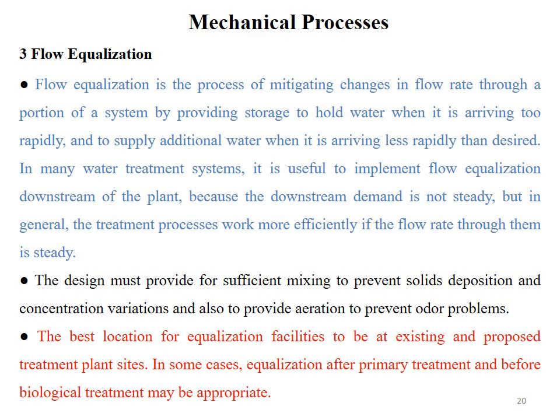And the best location for equalization facilities is at existing and proposed treatment plant sites. In some cases, equalization after primary treatment and before biological treatment may be appropriate.